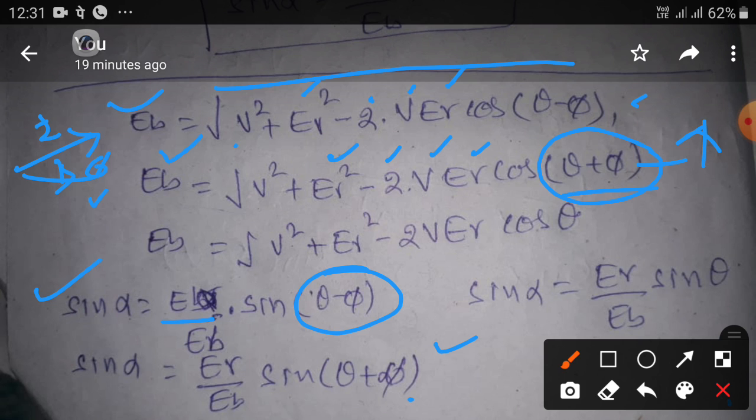The remaining motors draw lagging power factor, and when both are combined, the power factor may not be unity, but they will maintain 0.85 or 0.86. They escape the penalty from the discom.